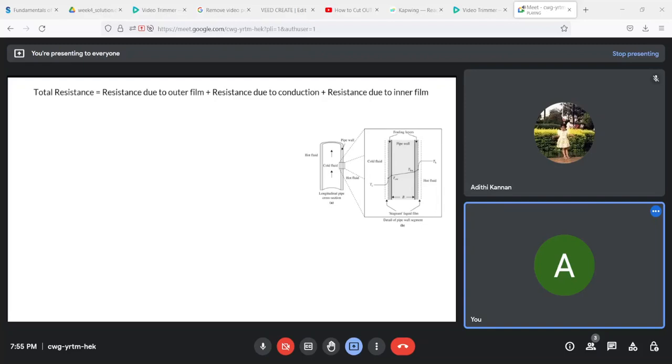So for the entire thermal process, you can actually write it as Q is equal to U into delta T. That is, heat flux is equal to U, which is the overall heat transfer coefficient, and delta T is the temperature difference. So this U will actually contain all the processes, the two convections and the conduction process into consideration, which is why in all these previous problems we've been dealing with the entire overall heat transfer coefficient that includes all of this. The moment you have separate heat transfer coefficients given for each of these processes, you need to add them up, calculate U, and then proceed with the problem.